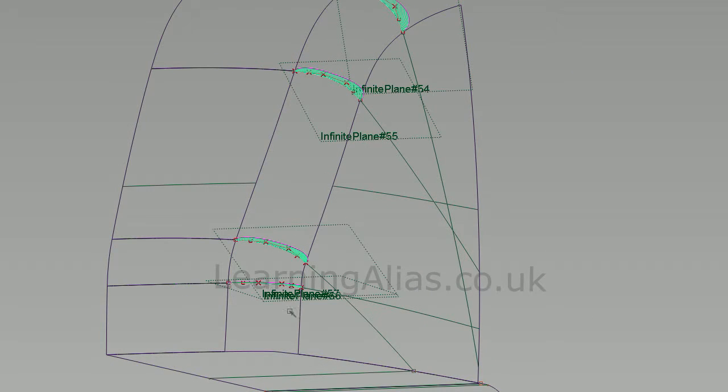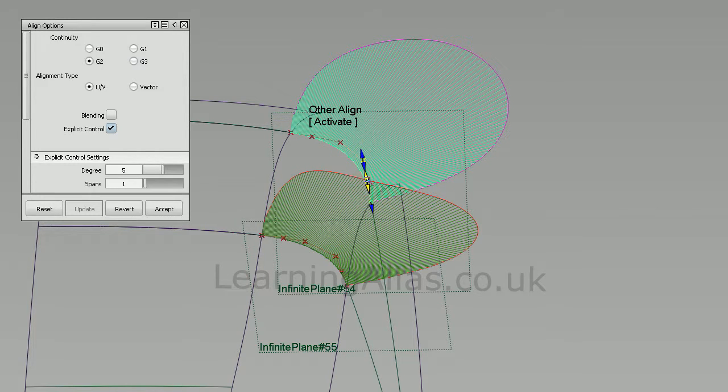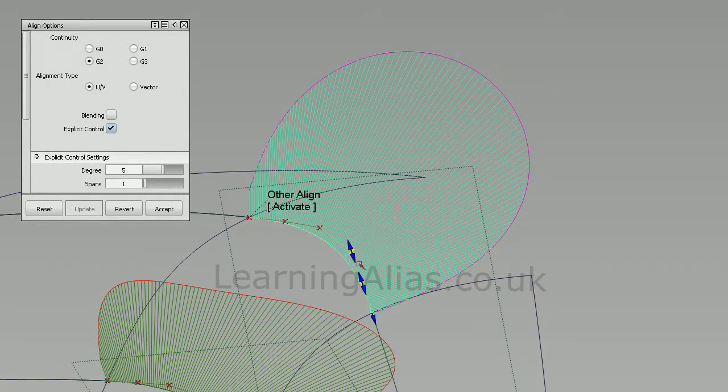Putting the combs on the curve shows us these can be improved a little bit. They're a bit uneven and have a flat spot. So using the align tool, you can click on the curve and it will re-invoke the history, and you can tweak the curve to get a much better, much more even and a nicer crown on our comb.